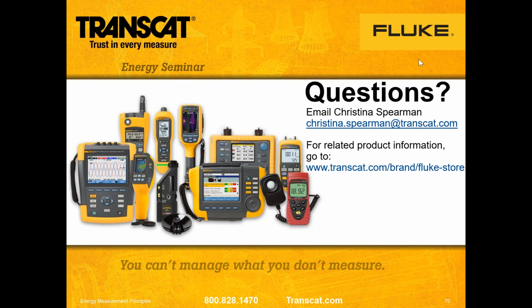What product would I use to find electrical waste? So that's obviously, I think we illustrated multiple times over, a power analyzer. Something along the lines of a 1738 or a 435 series type product has a full suite of capabilities to find these things and quantify. And again, put a dollar figure on it. That's the biggest thing. So we can actually put in your kilowatt hour rate, and we totalize energy, we'll totalize dollars as well. So you can see how much energy and how much money an individual load is using within your plant.